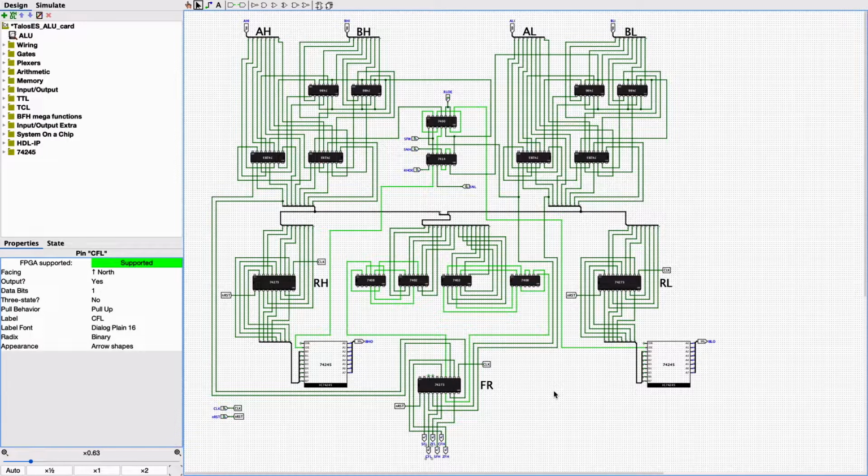And the other is the sign flag, which is just the most significant bit of this register, which is bit 7 here, which also comes from there. Bit 7 here comes down this line, wraps around here, and then comes out as the sign flag low, which is here.